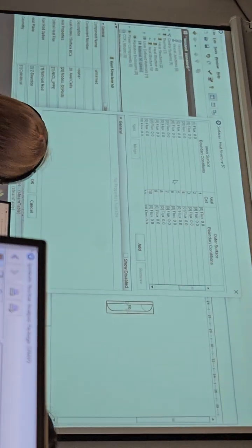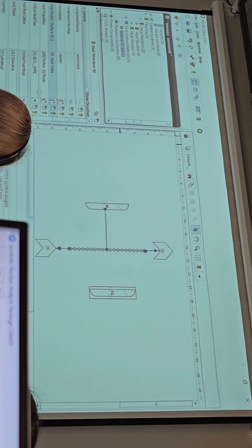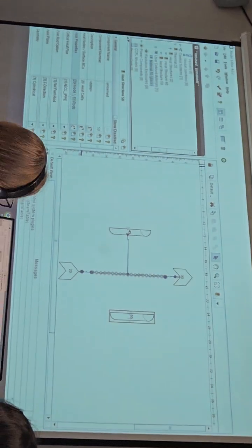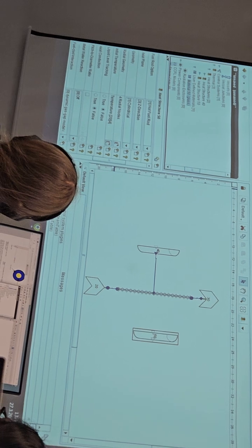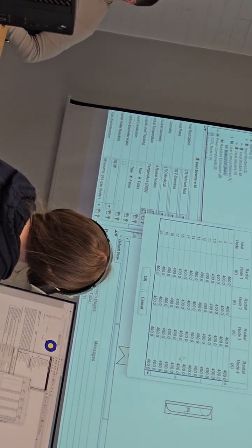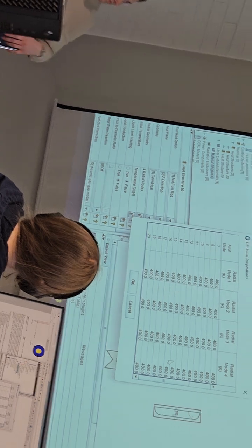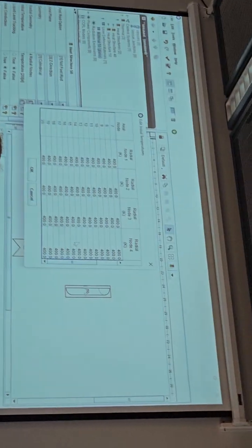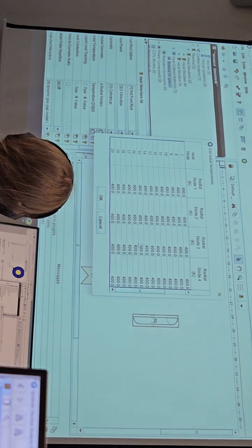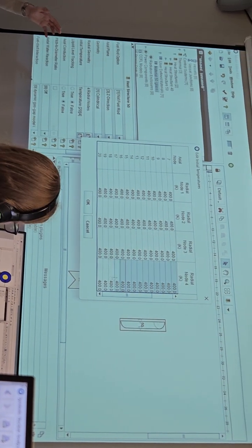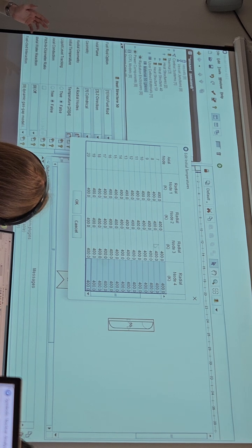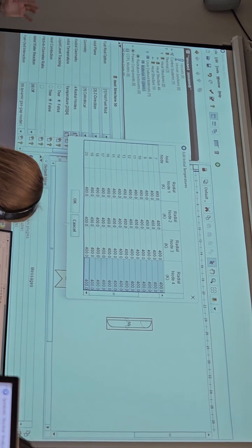We defined this already here. Temperature, yeah, it is a default one, 400 for all the cells. Since we know the outer temperature for the atmospheric air is 300, you can take 300 for the outer node and then intermediate values, but we can use 400.